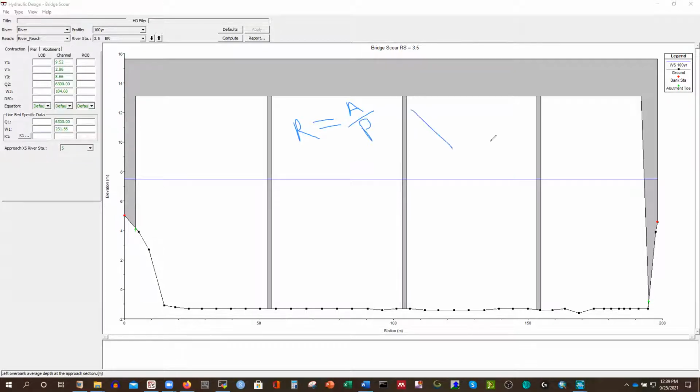Perimeter. If you have a section like this one, and if you have a flow depth of water there, right, that is the water symbol. If you have Y, right, so that will be the length of P. P, that is the length of P. You need to know the slope of this side and this side. Usually these are the same. And if you know the area of this cross section, and then you divide this cross section by P, then you will get the R. So this has to be this Y1.